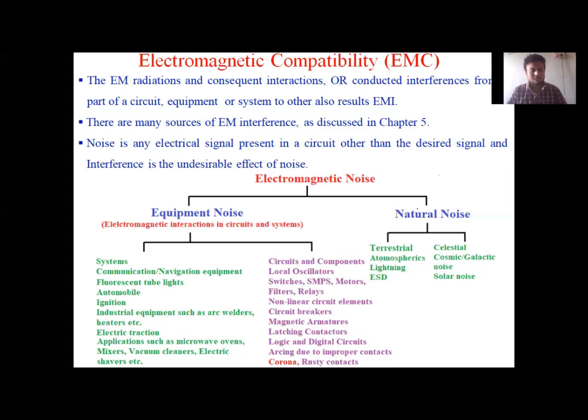subject in 6th semester. So if any antenna dimensions are much smaller than the wavelength, then that antenna is called a Hertz dipole antenna. What is the characteristic of a Hertz antenna? Hertz antennas are those antennas whose maximum or largest dimensions are less than lambda by 10, and they are not good radiators because the radiation resistance offered by that antenna is very, very small. So it is not radiating good power into the space, and it is not receiving very high power from the transmitters. So they are not good antennas.